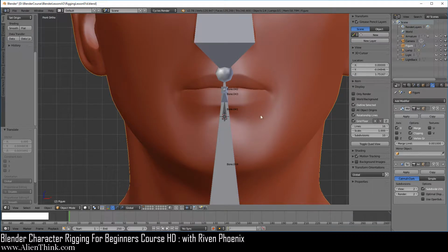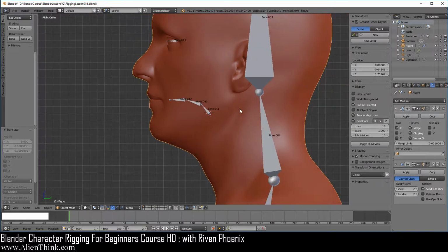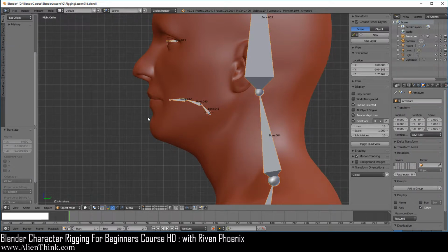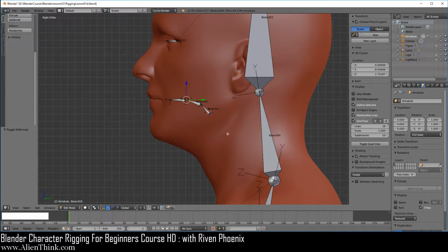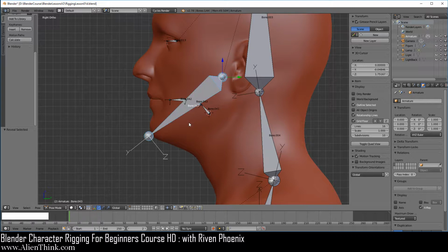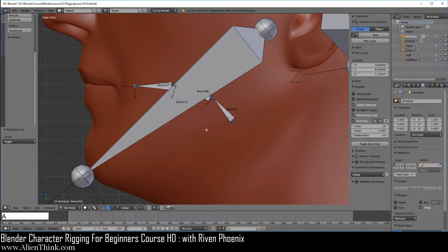back on. Now you can press the 3 key to go to the right view. Now we're going to bring the bones back, so click on the armature and make sure you go to edit mode and then do Alt H to bring the bone back, and now go ahead and click on pose mode over here and do Alt H to bring the bone back. Now we can just switch to edit mode over here and then A to deselect.